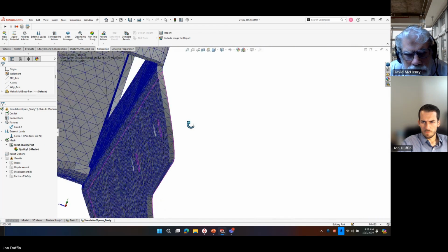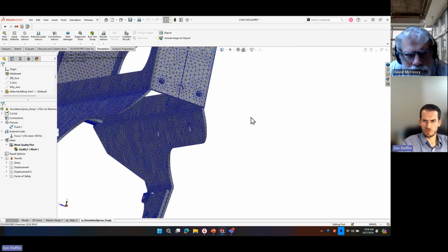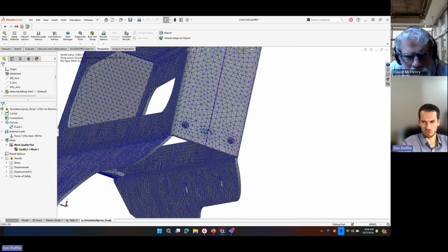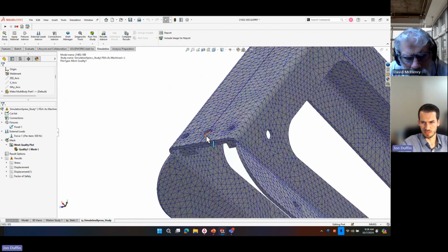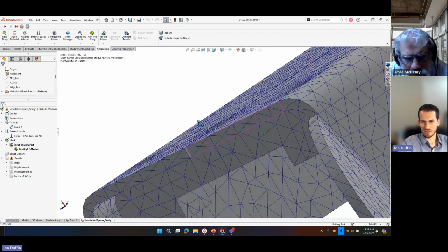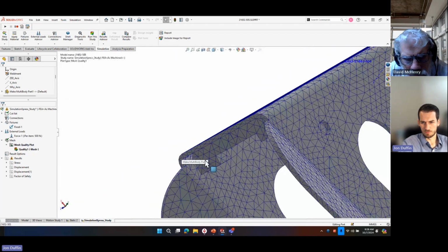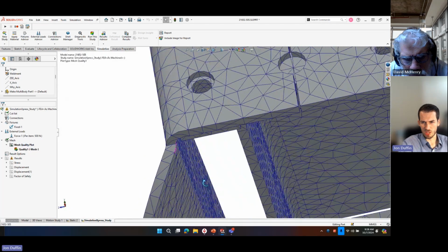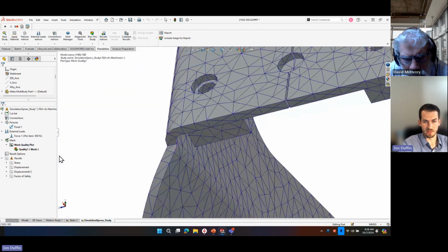All right. Yeah, so this one, I had to go into full sim to change my mesh controls on it here, just because it's so small. But that's going to be the root of it. I look at these mesh elements that are on here, and this is when I made it about, it looks like about 5 or 6 times denser than what that initial one was.